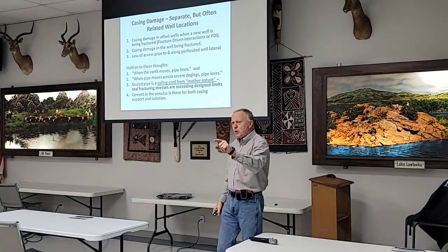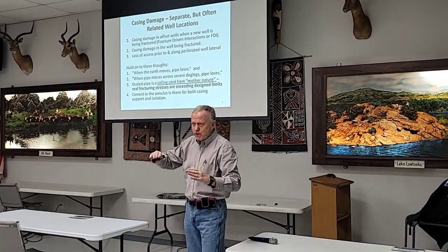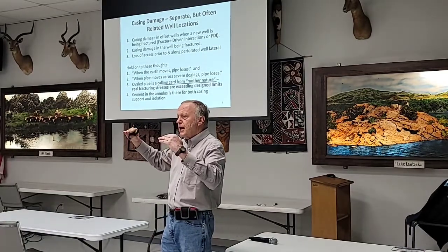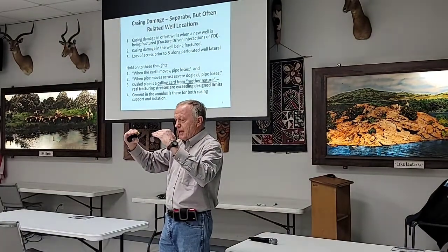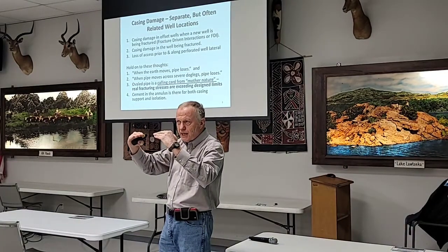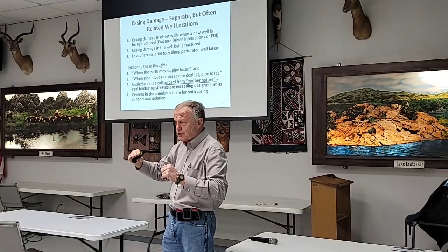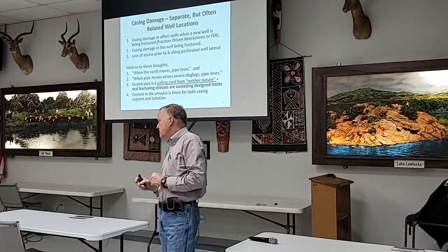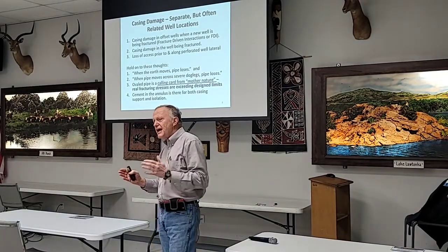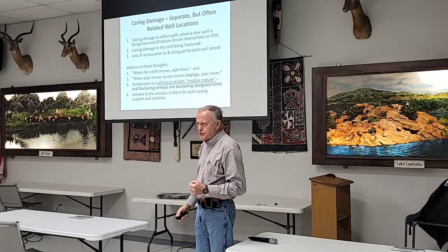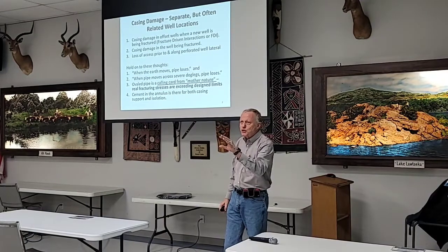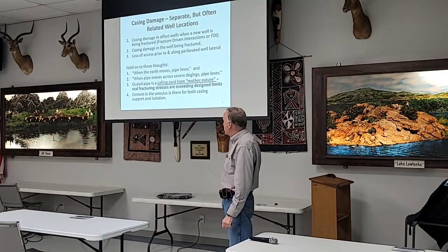But it's not only faults. Many of these, especially shales, have bedding planes and layers in here, and if those get fluidized, shale will creep. Doesn't happen very fast normally, but if it does, it will start pushing on casing. And when you go back in for refracs on some of these shale wells, you're going to see this. You're going to have a tough time, even after you squeeze the perfs, getting that frac plug down there in some cases. So it's good to run a fingered caliper down there to see what you have beforehand. That saves you a lot of problems.